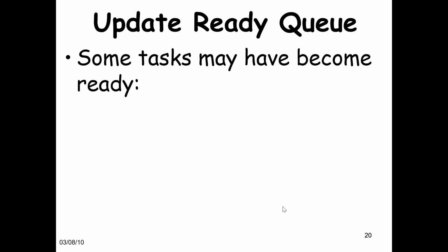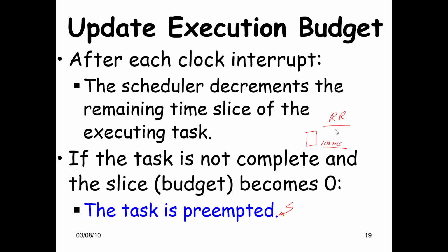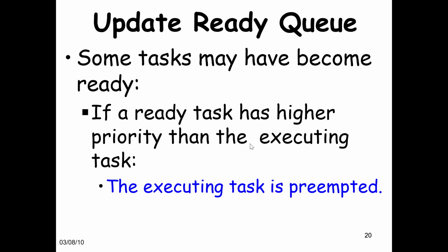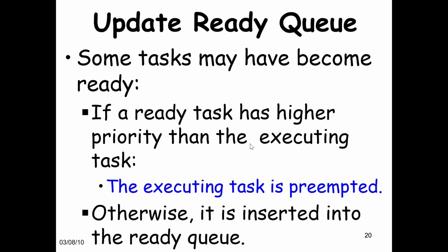So, if you would recall, in an earlier lecture we discussed the case of round robin scheduling. Let's say there are 4 processors and there are 6 tasks of the same priority and also of the highest priority. Then we decide a time quanta, 100 milliseconds in this case. We run a task for 100 milliseconds, then we preempt it, then run the next, and so on. If there is a higher priority task, of course, then as per EDF and RMS, a preemption is necessary.